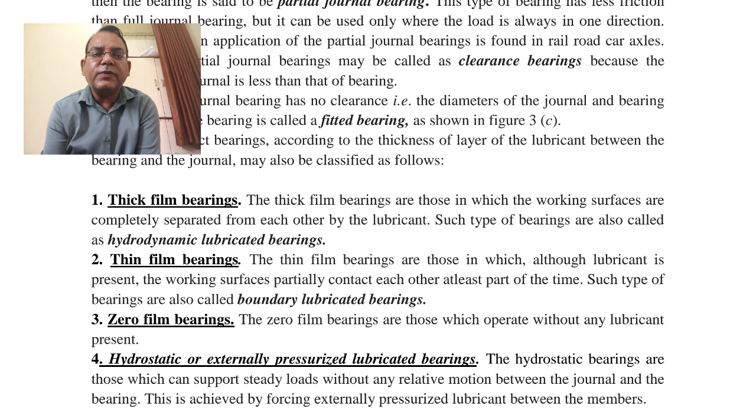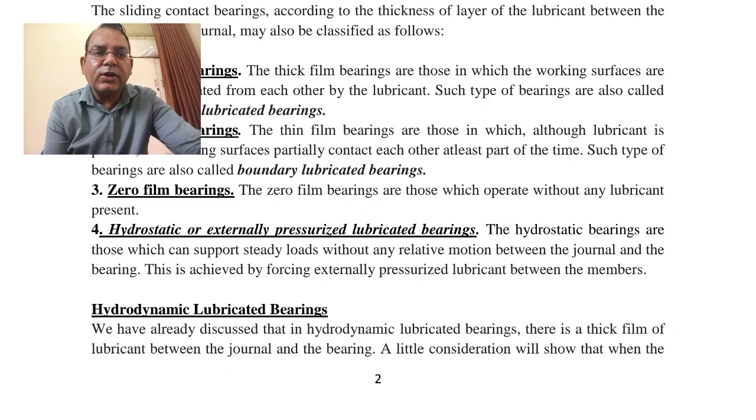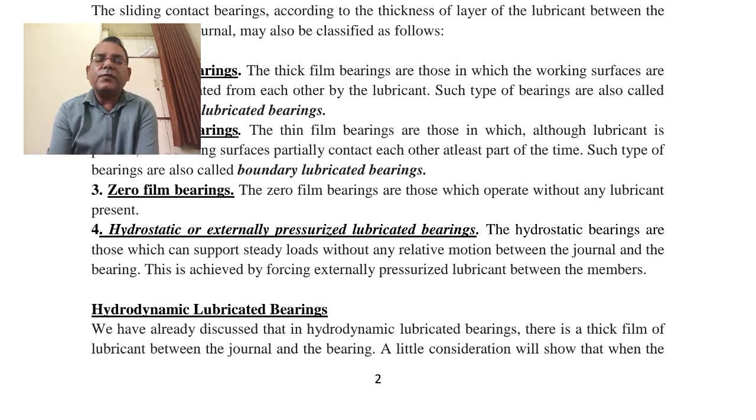Now, thick film bearing is classified into hydrodynamic bearing and hydrostatic bearing. The basic difference between the hydrodynamic bearing and hydrostatic bearing is that in both, the surface of the shaft and bearing are separated by lubricant, but in hydrodynamic bearing the concept is that self-built, inbuilt pressure is built so that it can separate the surface of the shaft and the bearing.